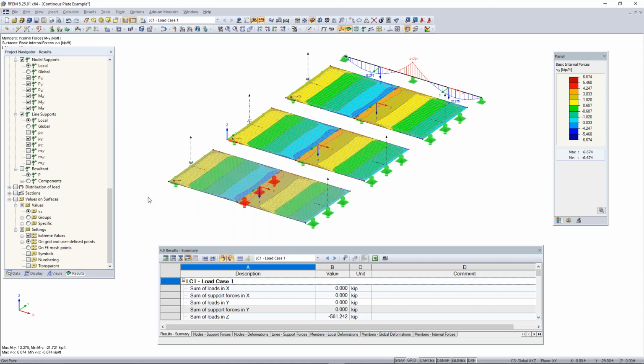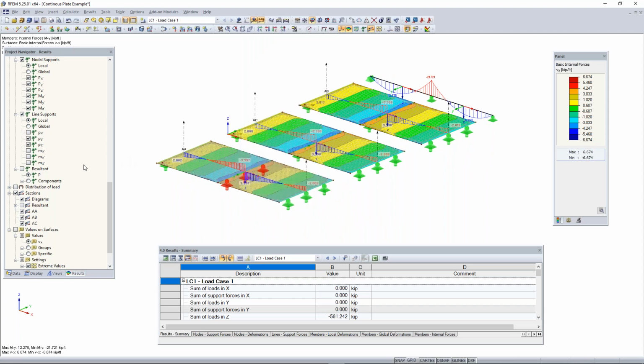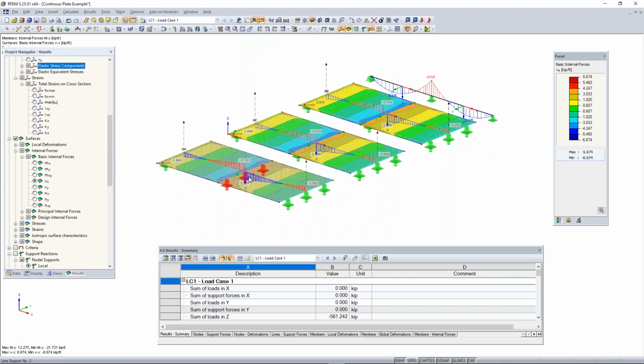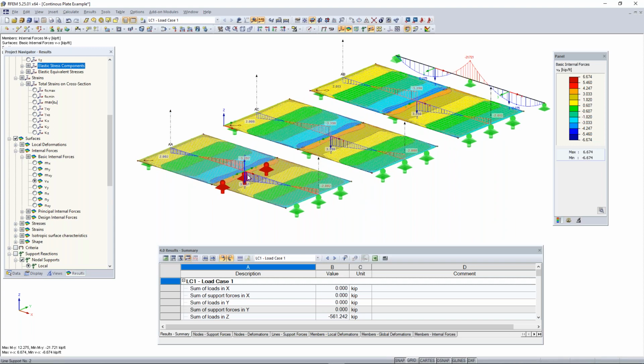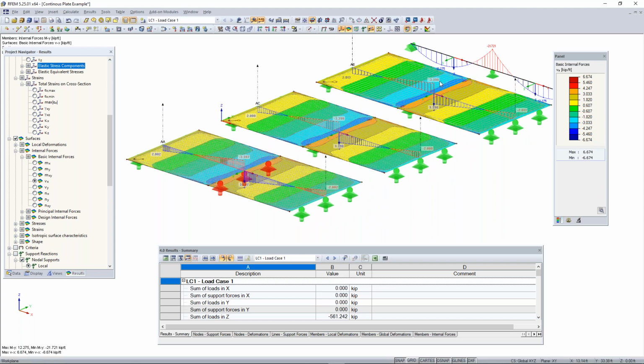So now that we've gone over the results, we can take a better look at the results and activate the section cuts here. Now that we added the section cuts along our surface, we can turn those on. And now we can see what the shear of the surfaces are with a shear diagram and that section cut plane. So right now, you can maybe get a better look at how those results differ in accuracy between these different plates here.